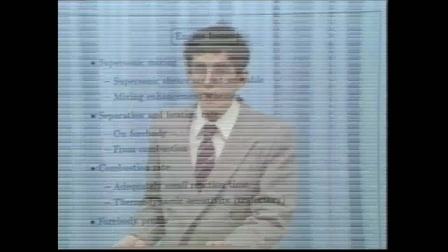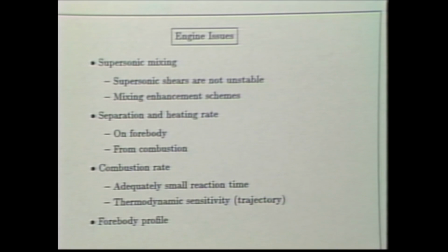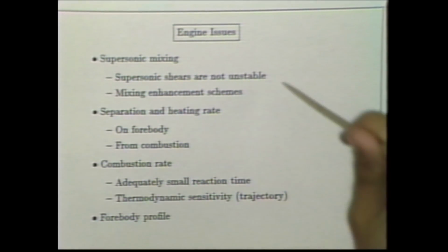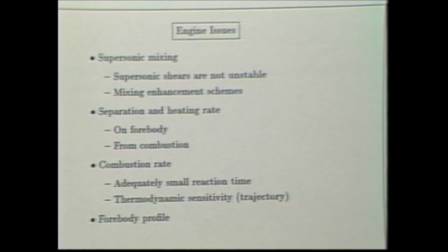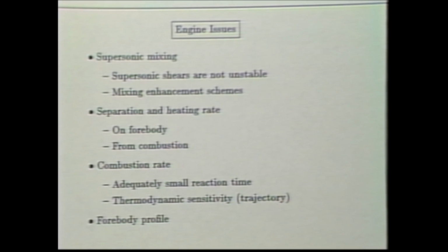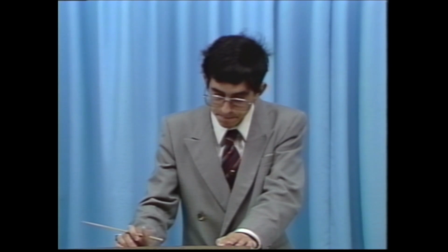Okay, I mentioned that there are a variety of other issues. One of the key issues associated with scramjet design is getting the fuel to mix. It turns out one of the most difficult problems in hypersonic flow and hypersonic engine design is getting the fuel to mix before it blows out the back of the engine. And indeed, this is a problem that comes right out of the fundamental flow physics. Let me give you a very, very good, simple, fundamental argument for why it is so difficult to get the fuel to mix.